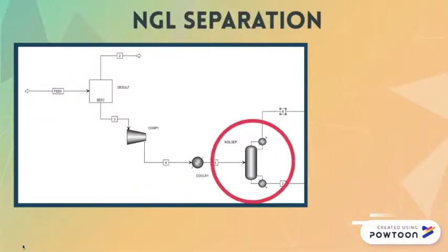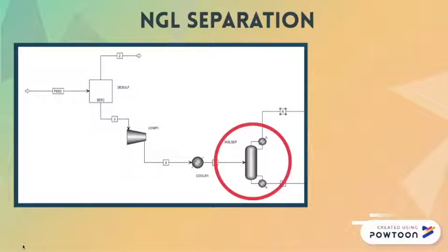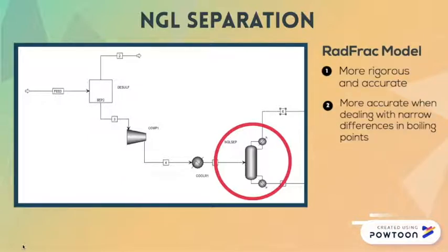For the separation, a RadFrac model was chosen. This was due to its rigorous nature and high degree of accuracy, especially when it came to components with narrow differences in boiling points, like we have. Thus, it was better suited than the alternative DSTWU model.